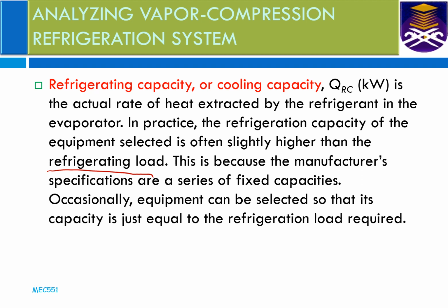So if it's just equal, then through the years of operating, the efficiency of the refrigeration, or the heat exchanger, will reduce due to a few problems, for example the fouling effect, and the dusty operating condition. So that affects the overall performance, and then the refrigeration capacity will be reduced if you are using a similar capacity where the refrigeration load is equal to the refrigerating capacity.